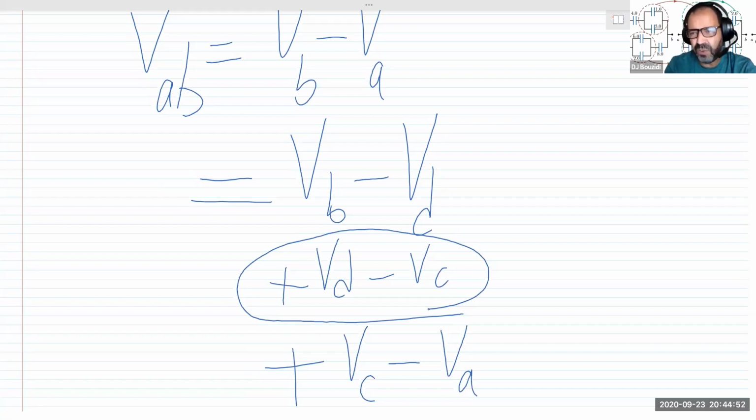So I reverted now, and I'm going to answer the last question first, trying to find what this voltage is. If I find that voltage, then I'm going to just apply the formula for the capacitance and the charge. The charge is equal to the capacitance, which is C2, times the voltage. And if I find the charge, then I have found actually the energy too. Remember, the overall voltage is 420 volts. So no matter what happened, this voltage cannot be more than 420 volts. It has to be less.